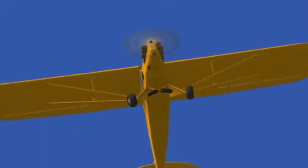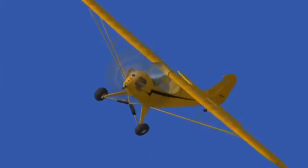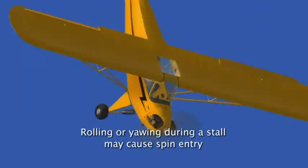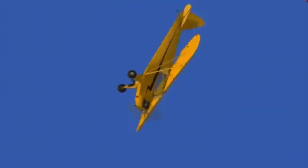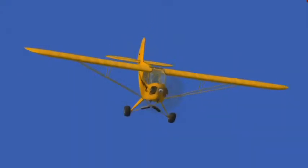As an airplane's wing increases past the critical angle of attack, the wings will stall. Lift will not be generated. However, if an airplane begins to roll or yaw towards a wing that is in a greater stalled condition, one wing has stalled before the other. This starts a rotation or a turn in the direction of the stalled wing. A spin has now been entered.